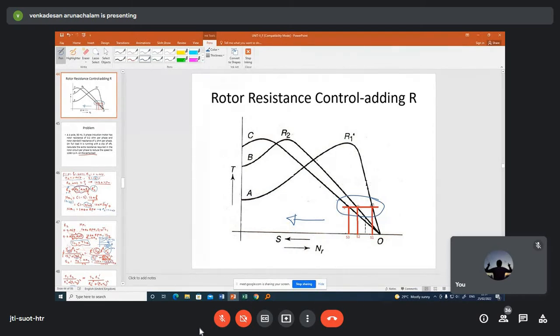but not as wide as you get with the frequency control method and V/F control method. This is a somewhat compromised method to get a wide speed control range, between V control and F and V/F control. So that is the property of this rotor resistance speed control method.